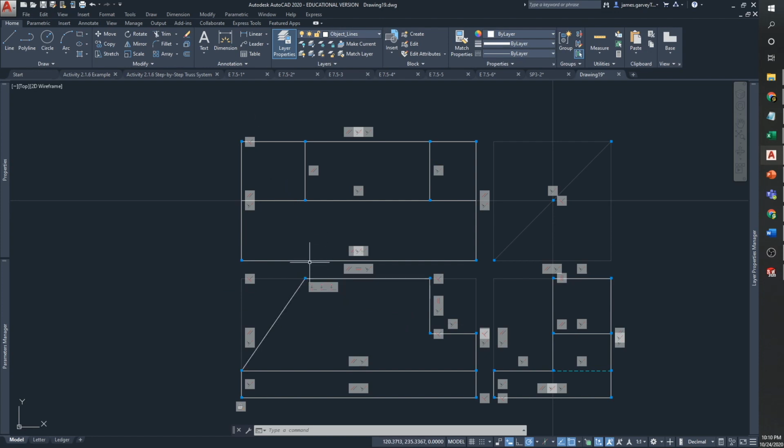There's no line here, so I can use vertical. So GC vertical, 2 points, so I can right click 2 points. So this point and this point need to always stay in line vertically. Hopefully that did work. Seems like it did.